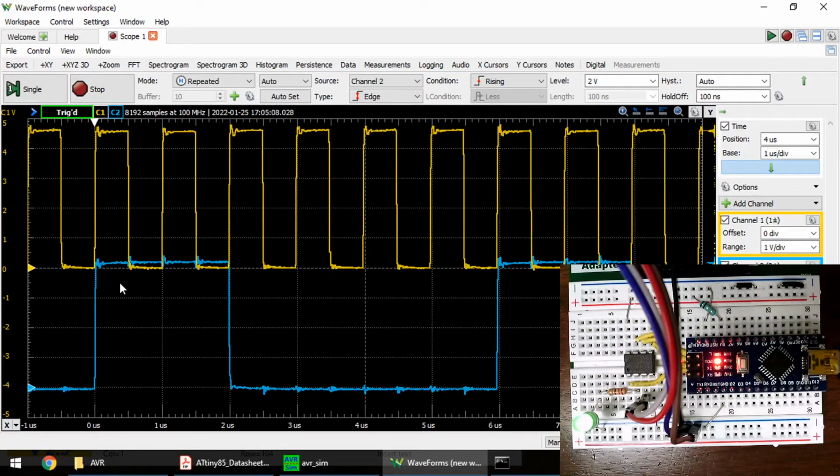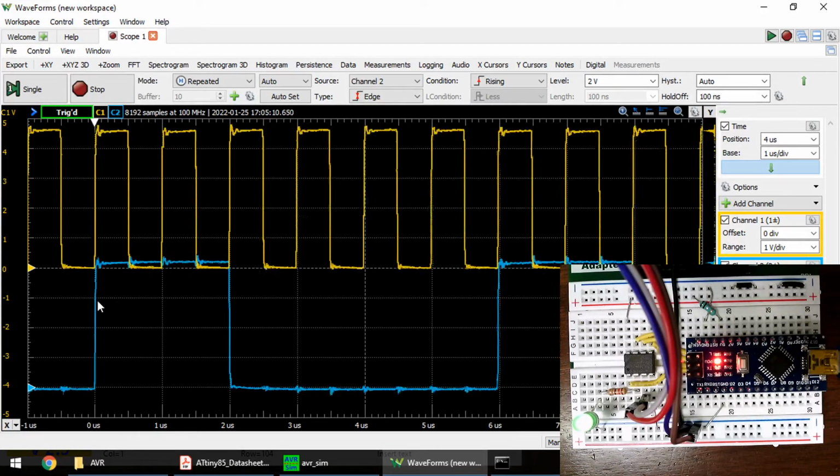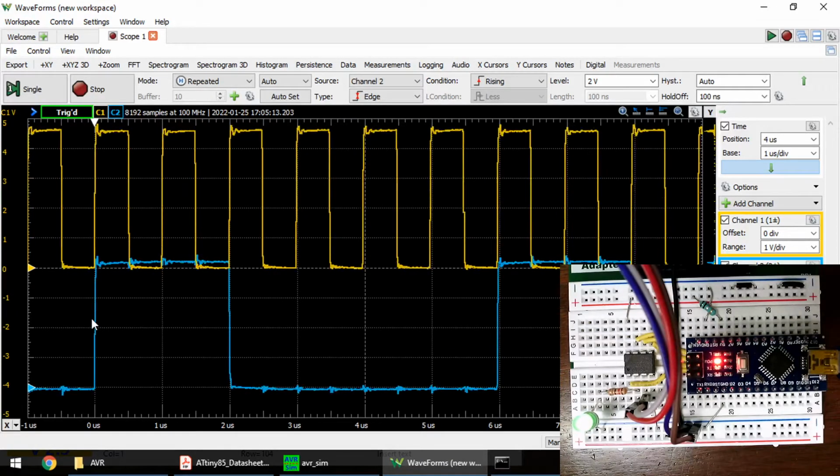After the instruction executes, it's not like we read the instruction and it turns high before we're done reading the instruction. I think the instruction is running, I'll go right here, and at the very end of that instruction, when we go to read the next instruction, this rising edge makes the data show up at the output register. So it's from 4 to 6 microseconds that our set bit high is actually being loaded and decoded. And then when we're finished after the second clock cycle, bam, it goes low.